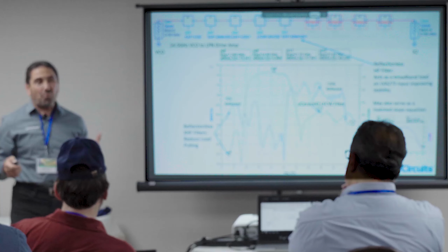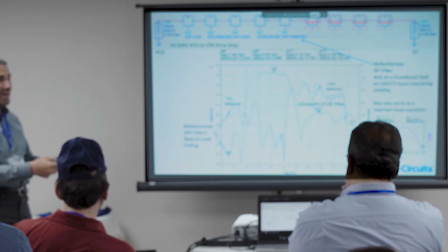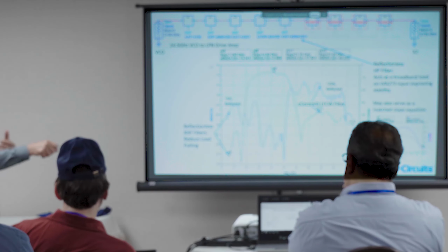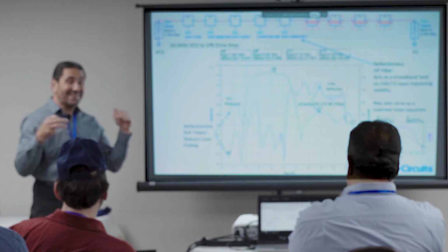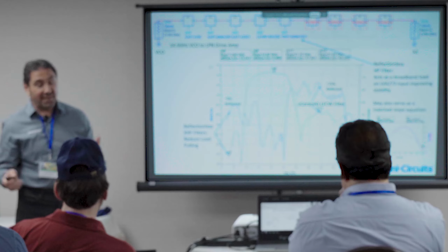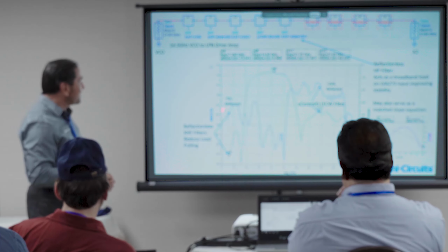That's very important when you're designing these multiplier chains. You want isolation back to the VCO. You don't want these nonlinear elements modulating the load back into the VCO. So this is a great filter to use in this application. Whether you've heard of it or not, I don't know, but I personally like them, as you could tell. All right, so that's here.